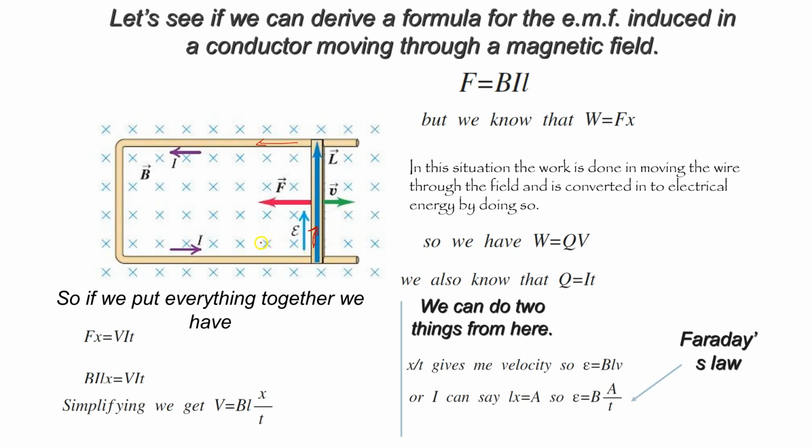So if you use your Fleming's left-hand rule, firstly your magnetic field is going into the paper, so your first finger should be pointed into the paper. Then you should identify that your current is going up into the air like this, so your second finger should be pointing towards the ceiling. Then your thumb automatically is going to point towards this side. So we know that is the force that will be experienced on the wire.